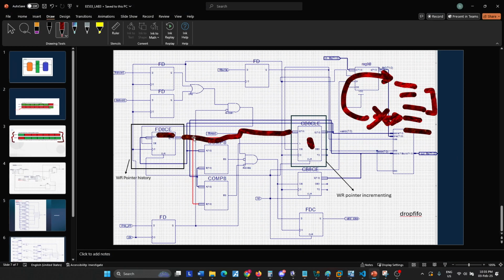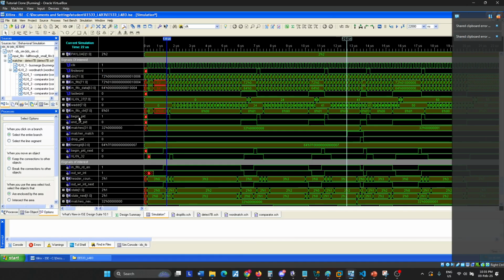Now XN27 is the history pointer's wire. Basically, this particular wire on the screen that is marked is XN27, which essentially is the history pointer. The WADDR is the write pointer of the dual port memory. This will increment the moment a FIFO is written into, followed by the control signals, the beginning of the packets.